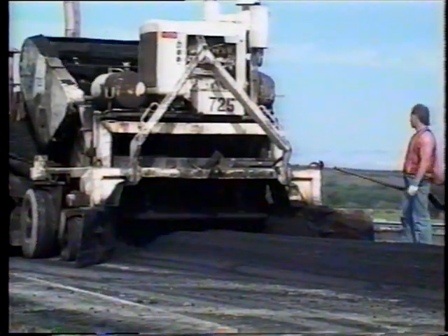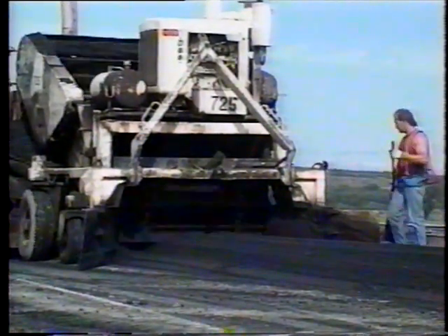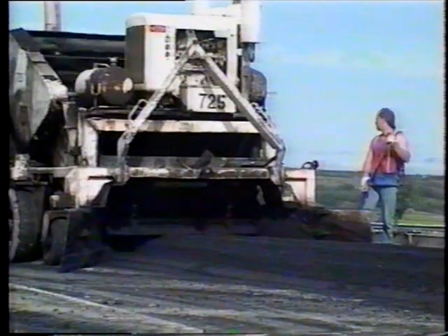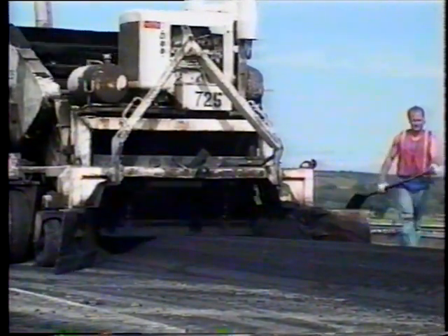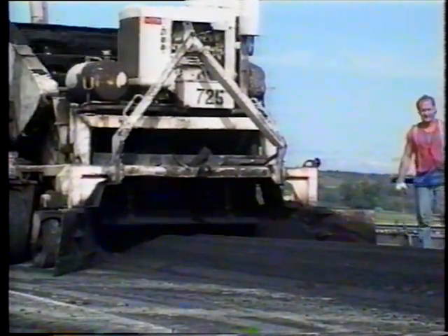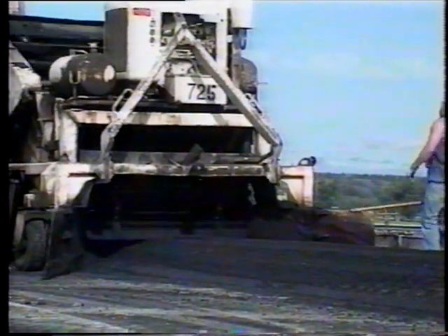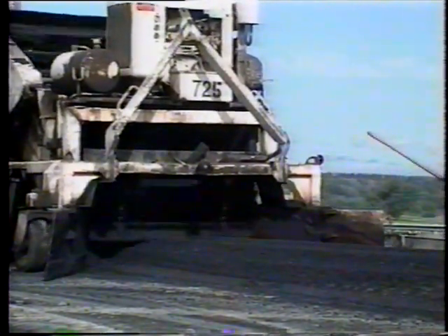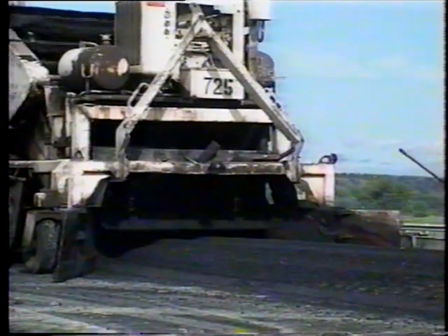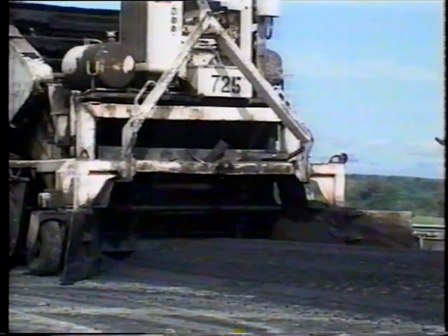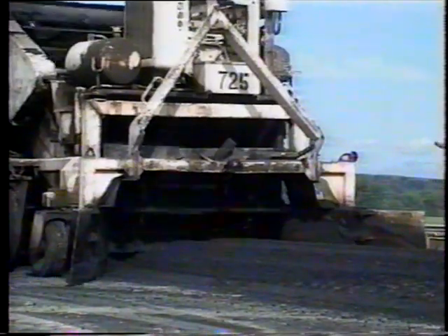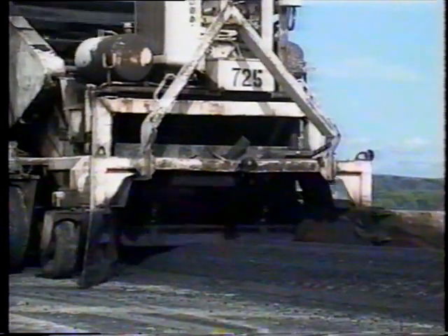When the windrow method is used, one of your main concerns is that all the mix is picked up. So see that the wings and the plate rest flat on the surface. If any material isn't picked up, have the contractor shovel it away from the wheels so it won't be run over by the pickup machine or the paver. From here on, your inspection concerns are the same for both methods.